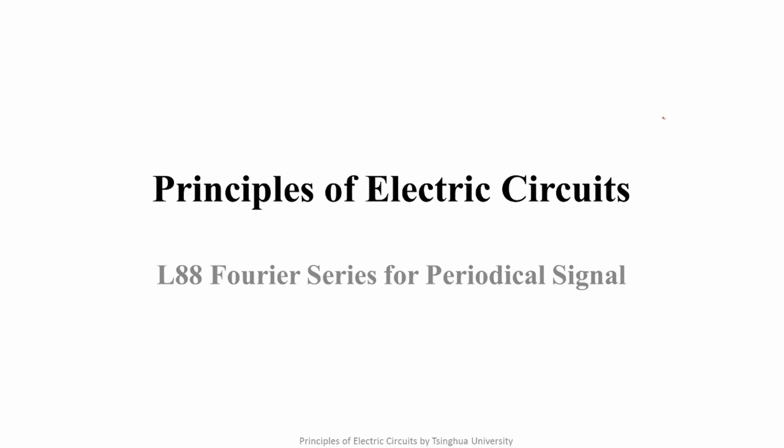But sometimes the excitation is a periodical signal instead of a sinusoidal one. We can use Fourier series to expand it into the sum of sinusoidal signals with different frequencies. The circuits discussed are all linear circuits, so the sum of the responses produced by the sinusoidal signals with different frequencies is the response of any branch in the whole circuit. This is the main content of the following three lectures.